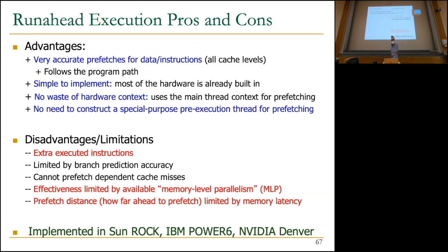Okay, but I wanted to give you a treatment of it because I actually spent a lot of time optimizing it. And I want to give you an example prefetcher. We'll see other example prefetchers later on that are not as capable. So stride prefetcher we've seen, for example. Stride prefetcher does A plus 4, A plus 8, A plus 12, A plus 16. That is specialized for a particular pattern. This is not specialized for any pattern. This is executing the program.